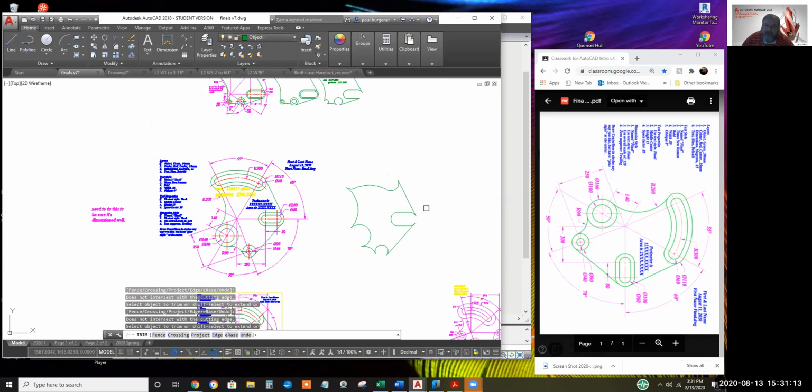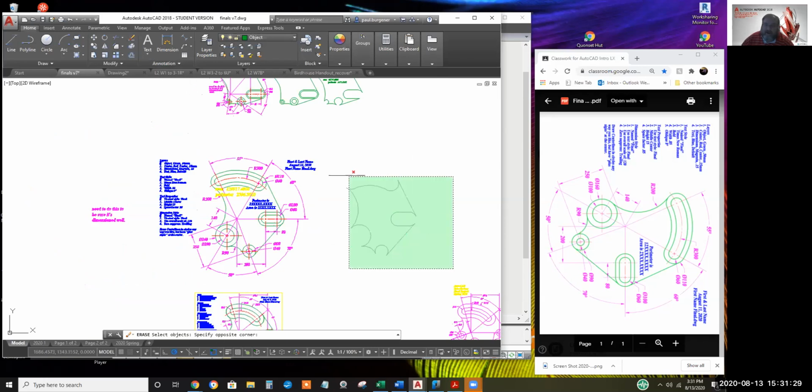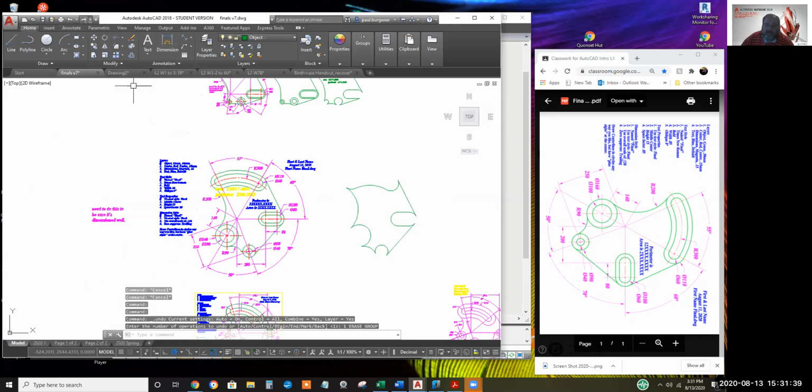And I got a clear shot now to weld these 1, 2, 3, 4, 5, 6, 7, 8, 9, 10, 11, 12, 13 pieces. Let's see how many there are. I'll begin any modify command and select them all and hit enter. 14 are found. I'll undo to restore them back again. 14.